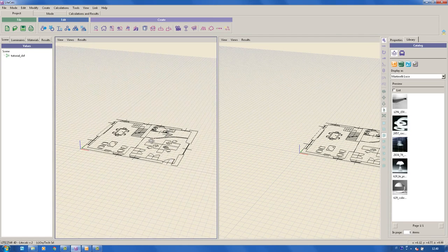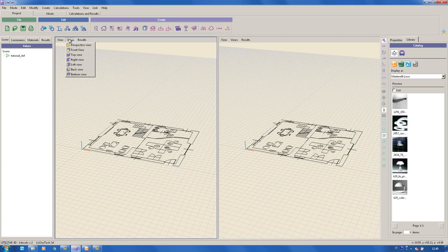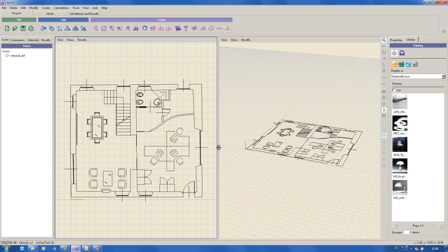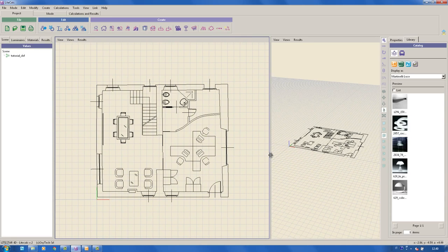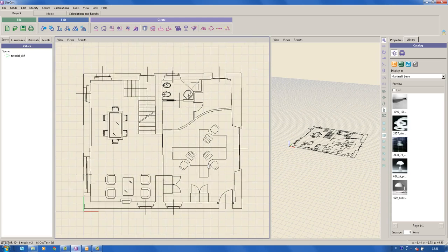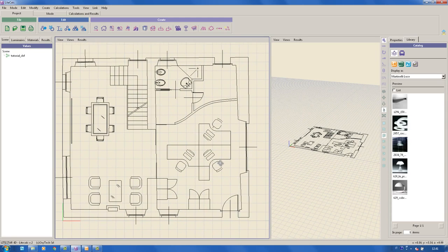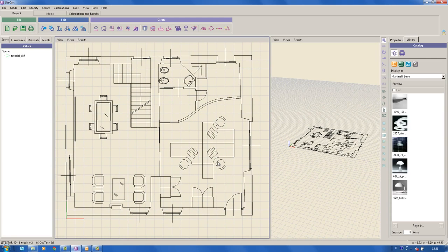To facilitate the graphical tasks, the program allows the simultaneous use of several views. Clicking on the icon Advanced Interiors, we will begin to draw the area, tracing the DXF directly with the mouse. By holding down the X key, the pointer will pull towards the design snap points.